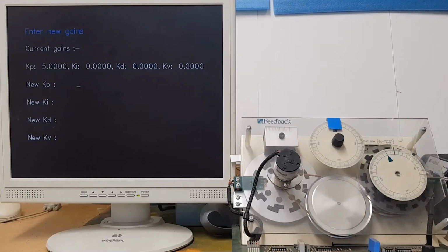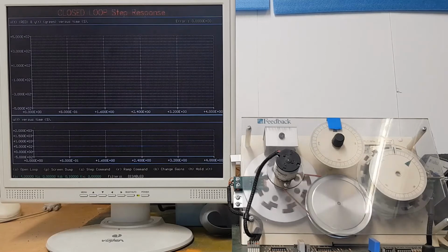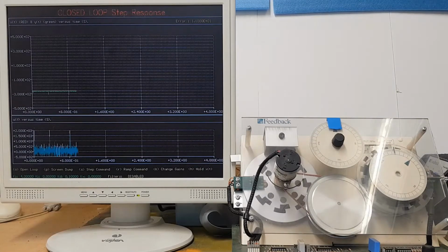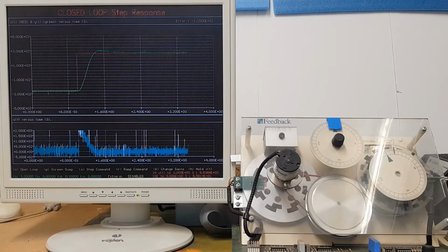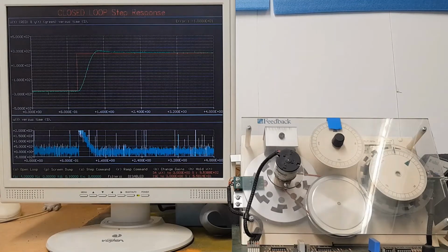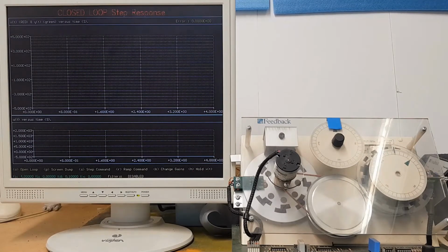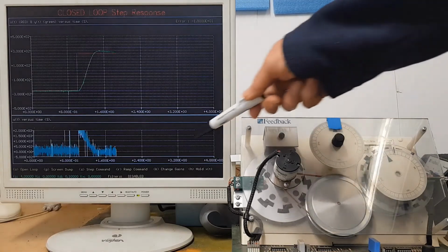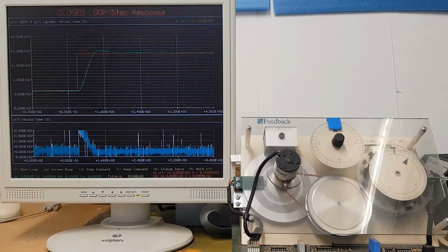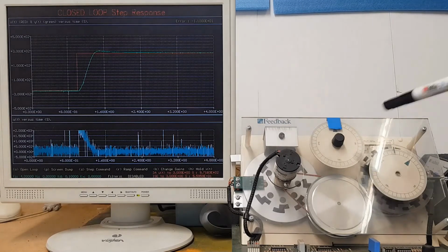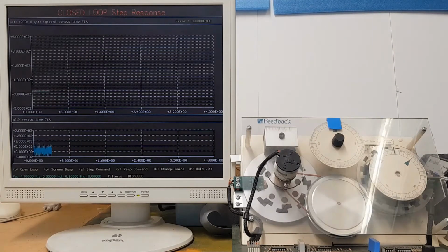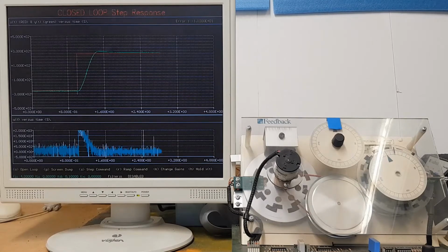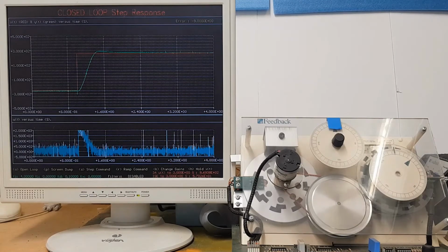And then if we put some numbers in there, let's say 40, 10, we can then implement our PID gain. So that's an example now of a PD controller running, and you can notice now that the signal on the output here is a little bit more bouncy because there's a little bit of noise in the rig, which you can see is like it's got a bit jittery. So this is our rig that we can experiment on.